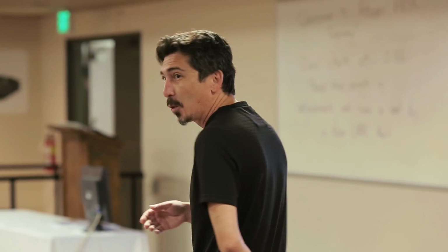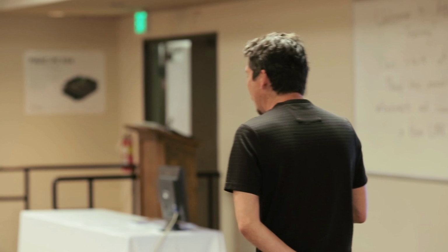It's quite general, so you can use it on pretty much 98-99% of your machines or axes. On top of that, of course, there's one more thing. Everything is in C. So you can write a user-written servo. Like in the old generation, you could also write what we call an open servo. Or you had to write compiled code, which had to be written in assembly, because it was using a digital signal processor.